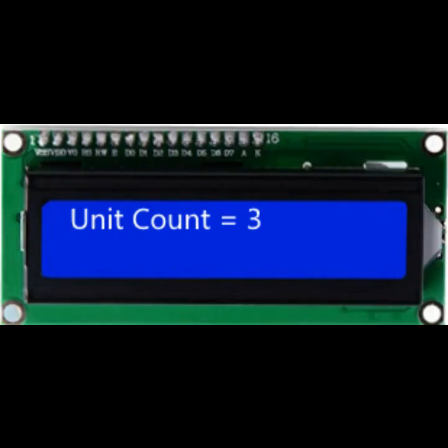Now we will talk about the different parameters. Unit count. This parameter tells the ACO how many units are connected to it. This only applies to the 3-unit model, ACO 3. If the ACO 3 is only being used on 2 units, connect them to inputs and outputs 1 and 2.